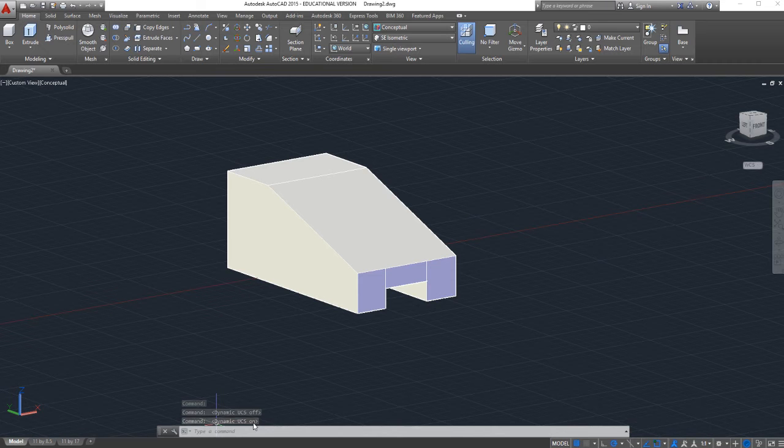What this does is it helps you, and it will automatically help you pick a face to draw on. Otherwise, you would have to use the 3 points. So right now, I would want to draw on this one. So you see how my X and Y went to this face, or I could come over here and I could click on this face over here.